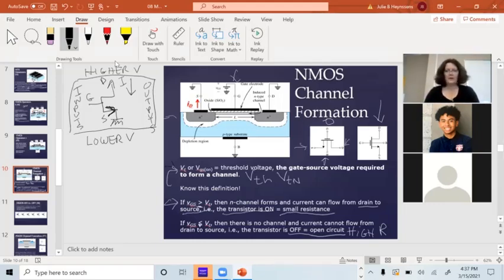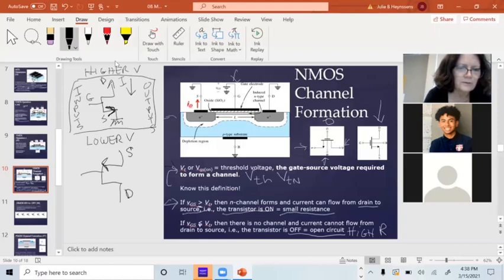When I draw a PMOS transistor, and I'm getting a little bit ahead of myself, PMOS transistors look like this. This is the little arrow, and they're drawn upside down. This is the source. The little current arrow always goes on the source. This is the drain, and this is the gate. Again, the higher voltage is going to be on the source of a PMOS, and there's a little bubble right here too. And current's going to be flowing downhill. So PMOS are always drawn upside down normally. Talk about the PMOS days.